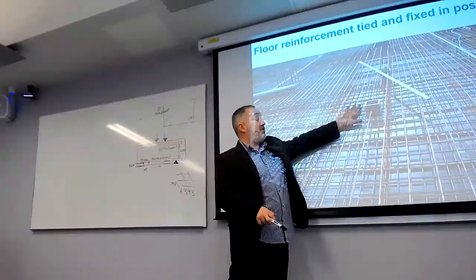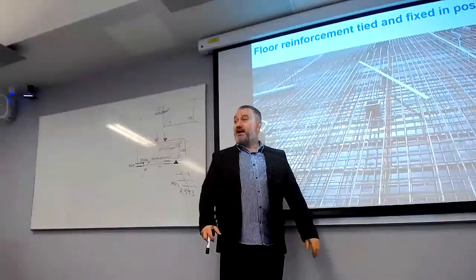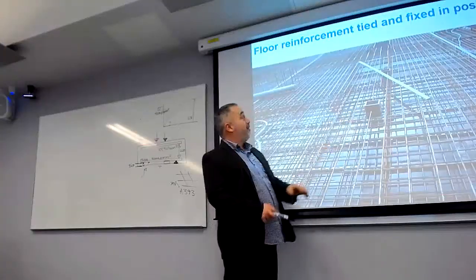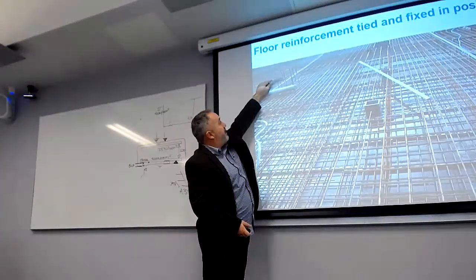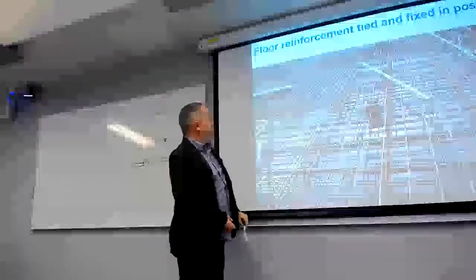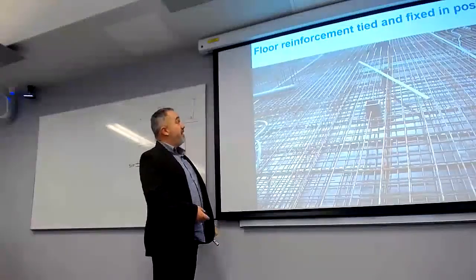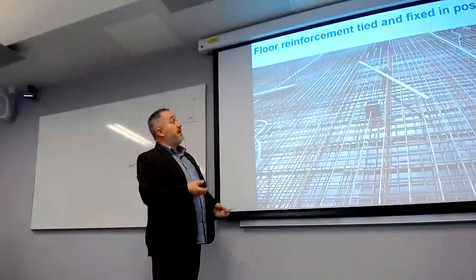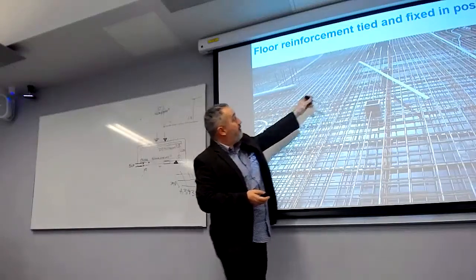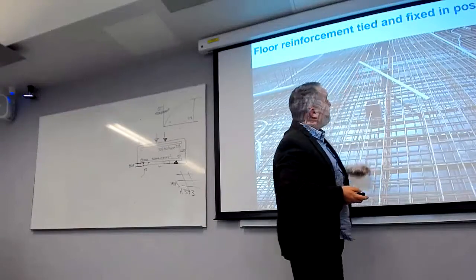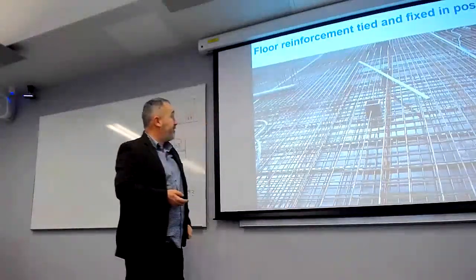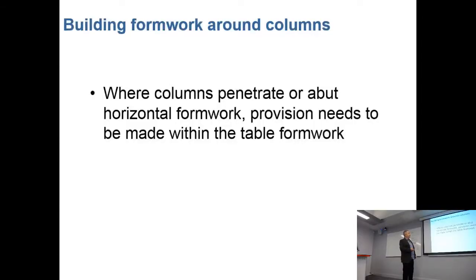Then once the concrete's gone off, you just stamp through the polystyrene, and you end up with a hole all the way through. We've also got some bars there, called starter bars, that you would be putting your column in place with. You can see we've got all of the surfaces going through, and there's a larger void there. So it's a good idea to try and create all of your voids beforehand.